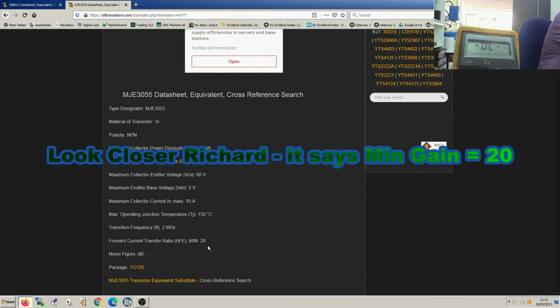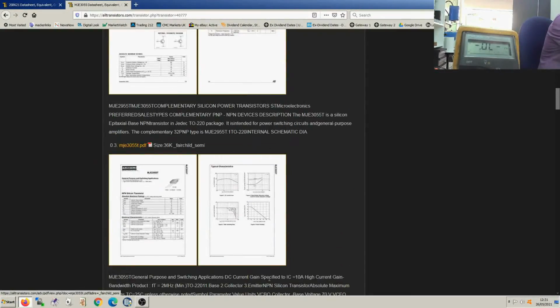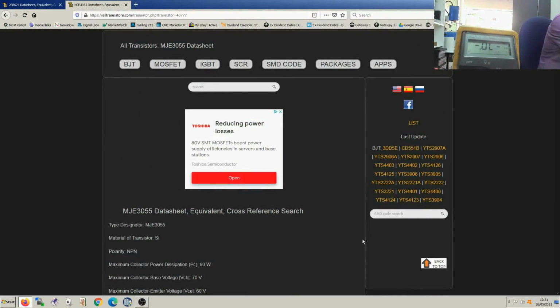The minimum, yeah. So maybe they're both okay, but this raises an interesting point: if there's more than one of those in the circuit, working together, I would be suspicious of that, and I would tend to try to replace them so that all of them have the same sort of gain, especially in amplifier circuits and suchlike. Those two transistors will not work equally together. If they're effectively sharing the load, in parallel basically, I would certainly consider that would be a problem.